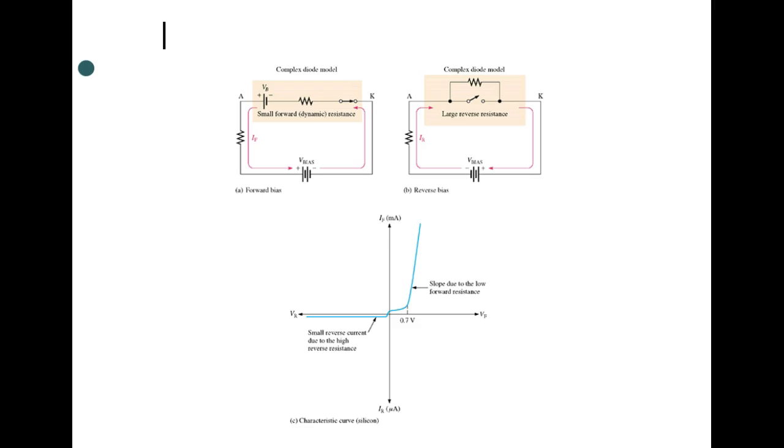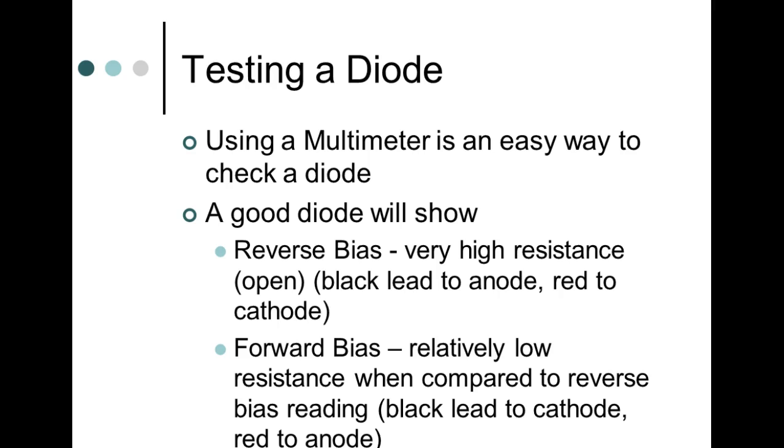So this is third approximation, which we're not going to use, thank goodness. Everybody okay? So testing a diode, using a multimeter to check a diode. If we're using an ohm meter, we're looking for a real high ratio between the forward bias and the reverse bias. It's still going to measure K. But one way it might measure 100K, another way it might measure meg, right? You understand? As long as we get that big old ratio between the forward and reverse bias, then it's okay.